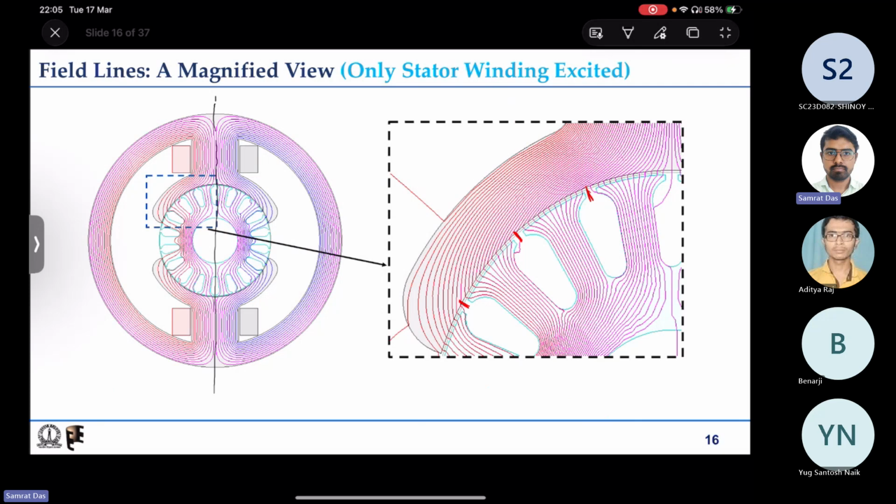If we take any flux line like this, then we understand that the MMF drop, half is here, half is here, and total, say this is IF and this is also IF, so 2IF is the total current enclosed. So IF gets dropped here and IF gets dropped here.